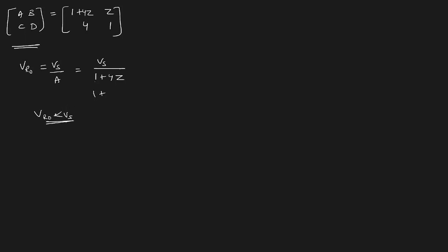Many people will analyze it this way, but there is a thing here: let us ignore the series resistance for some time. If you ignore it, Z will be j omega L, instead of R plus j omega L, and Y will be j omega C, right? If you multiply these, it will become j square omega square LC, which is minus omega square LC.